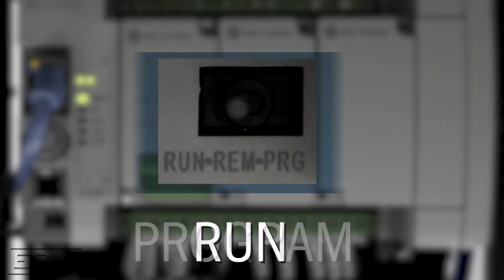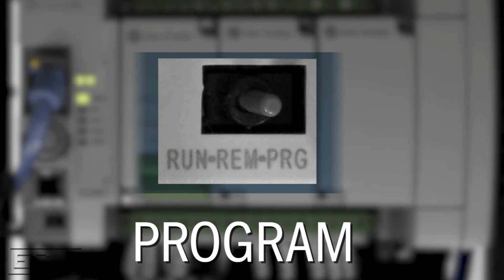at the device. The second position is program, which means the processor does not execute the logic and the outputs are de-energized. This mode is typically used for program downloads or firmware flashing, but it also requires someone to be physically present in order to change the mode.